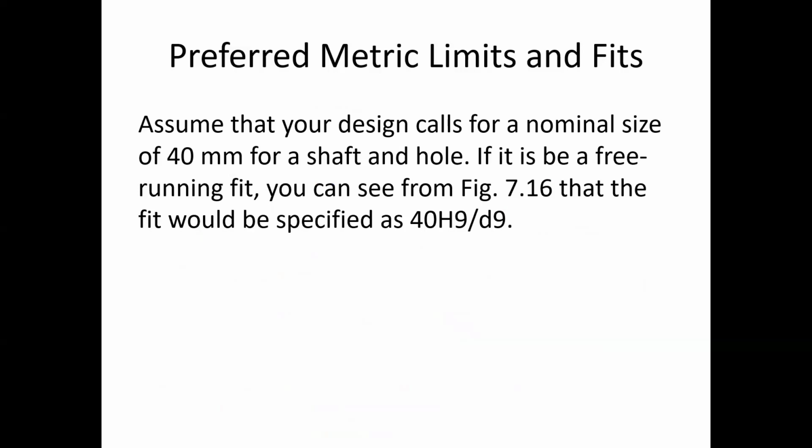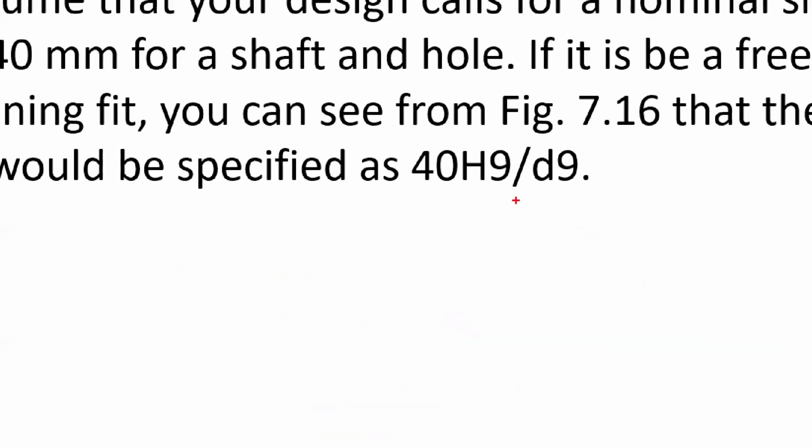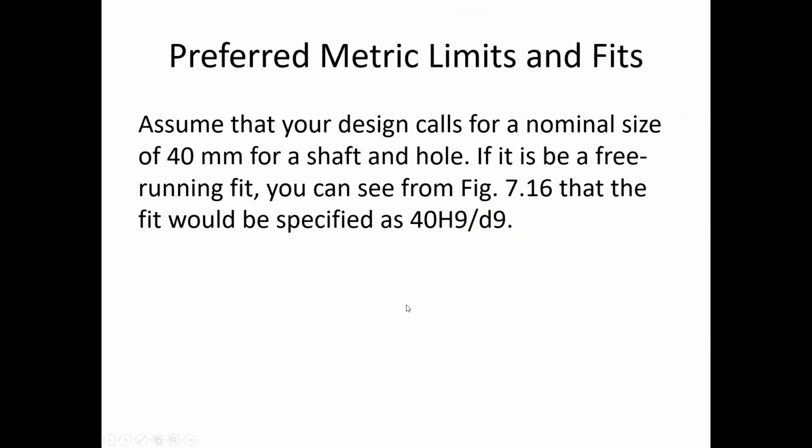A lot of times when you're drawing, you might see this diameter, and it might just be a hole, and it says diameter, capital H9. Or maybe you're looking at a shaft and it gives a diameter and it has this little d9. So the capital letter is the hole and the lowercase letter is the shaft. And this just happens to be H and D. There are other letters in the game. These are probably the more common ones you'll see.